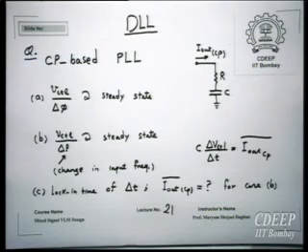That was the question. See, what do I mean by proportionality constant? You have a phase detector. Output of the phase detector at a steady state is proportional to the input phase difference, right? But here at the steady state, if you call it frequency equal to 0, at frequency equal to 0, the transfer function of this circuit is not stable, right? Because one pole actually is equal to 0. Therefore, we should look during transient when it is locking from one frequency to another frequency in the lock range.